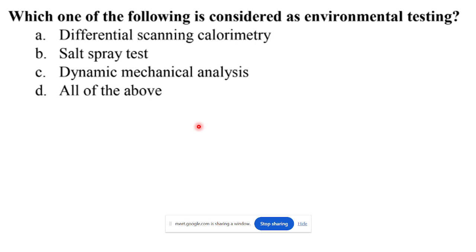So for this you need to check the FESEM image, whether the distribution is homogeneous or not. Otherwise, you cannot always get the same result if the dispersion is a problem. So if you made six samples, and you are changing one component, if it is a filler, I will suggest you check just the dispersion and distribution, then you will get some insight into what problem is happening there.